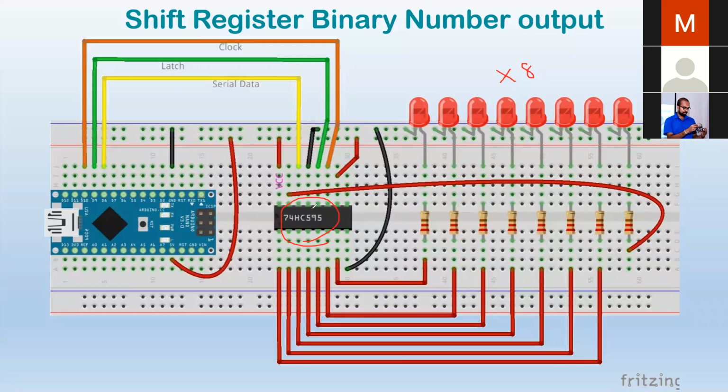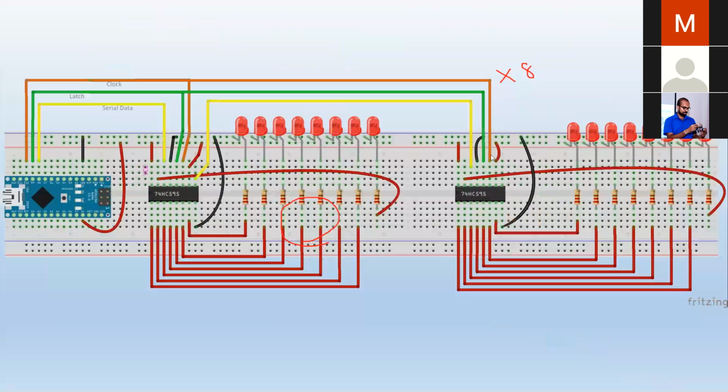To this chip, which is going to turn on these LEDs accordingly. And those pins, right? See, we are still using 3 pins, and we now have 16 LEDs. And if you want to do more, you can connect these things in stages, and they still work like that. This is what we call daisy chaining. It is a technique called that.